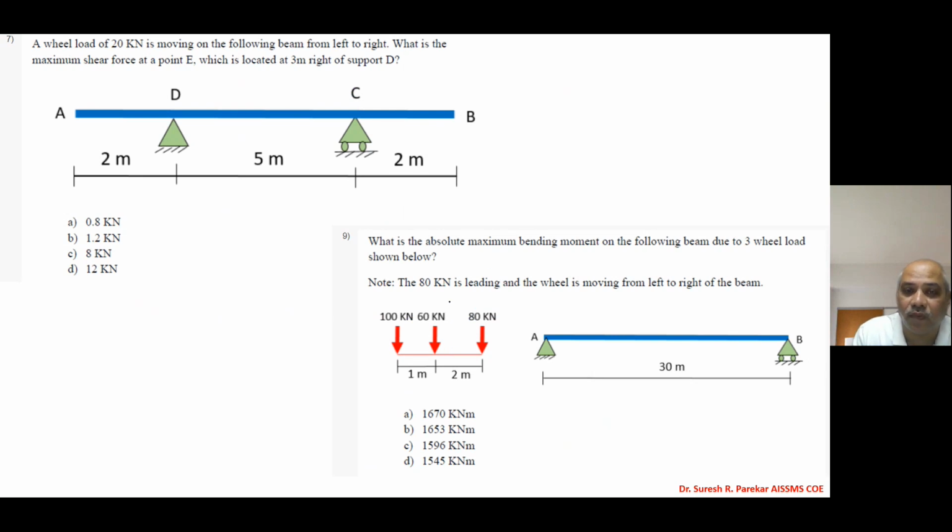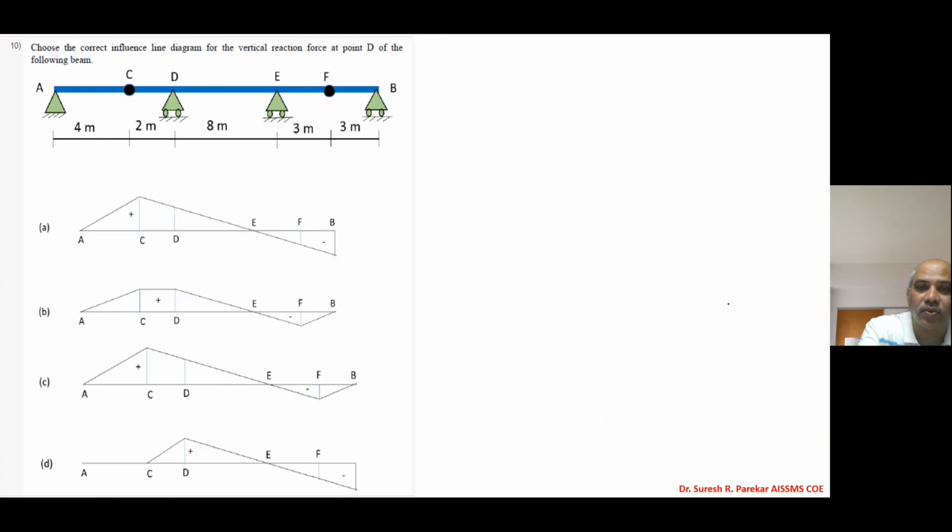a difficult one. You have to find the total load, the position of the total load, and then we have one of the loads, and your total load should be equidistant. So this should be X. And then we have to put this at the center. So this will be 60 and this will be the total load. And this should be X by 2, X by 2 from both sides.